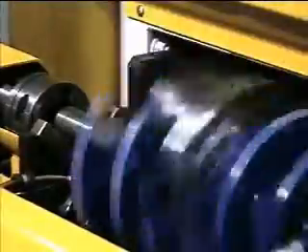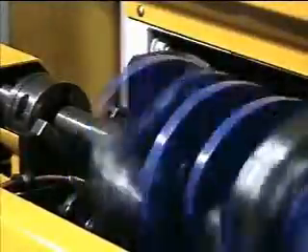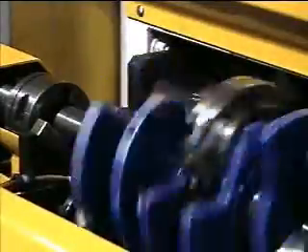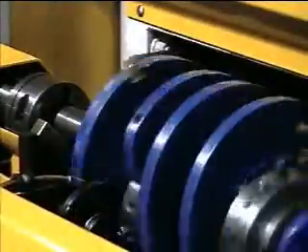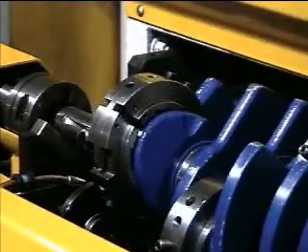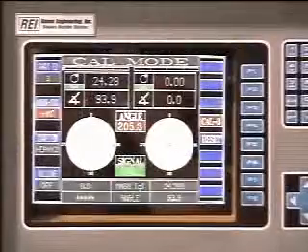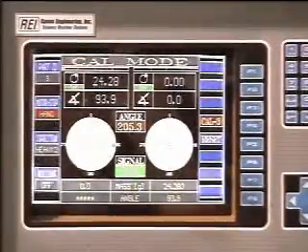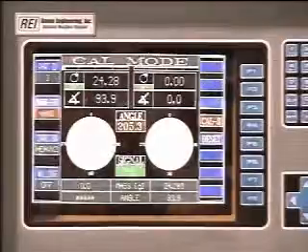The operator presses the start and common push buttons to begin another audit cycle. When the 2 conditions of rotational speed and signal stability are met, the audit is stopped. Advancing to Cal Step 3, the weight is transferred to the right plane and the audit process is repeated.